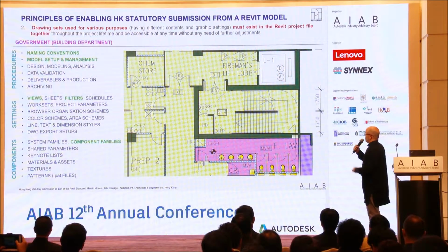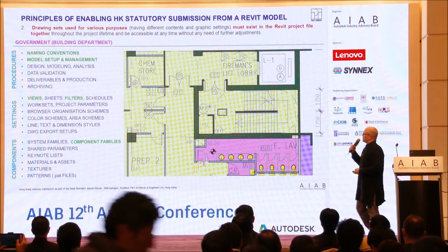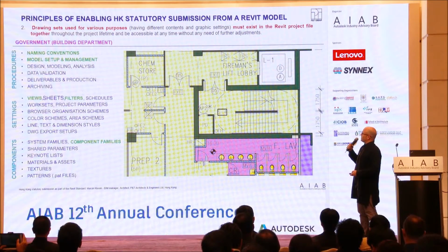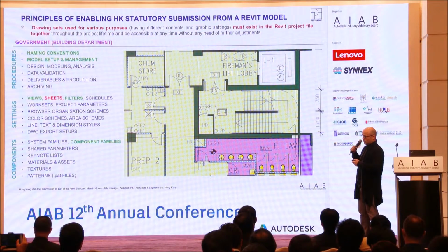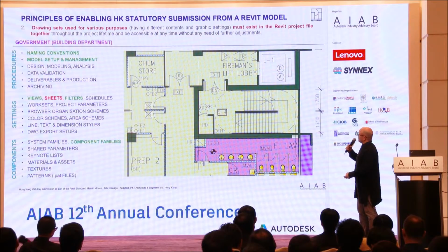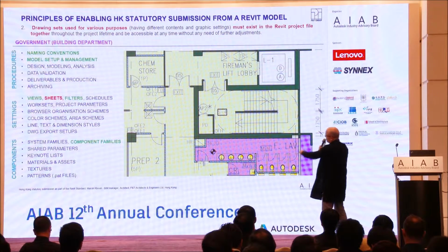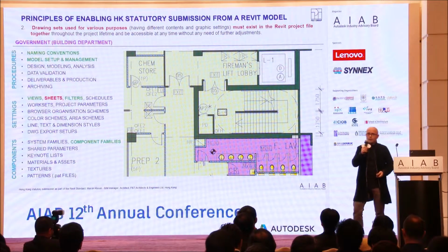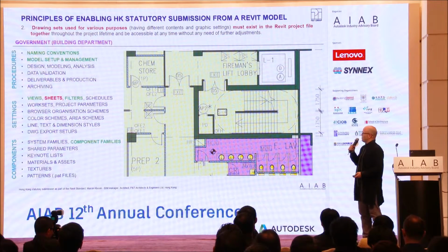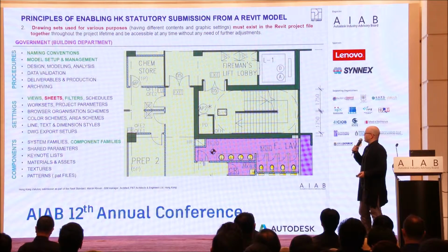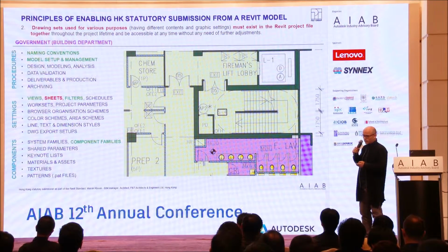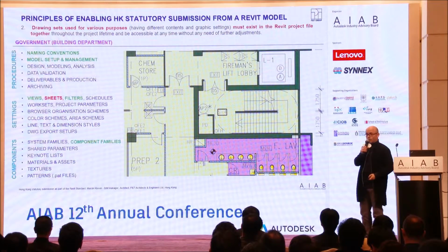Now for the standard GBP submission with colors, we need more than that: sheets. Why sheets? Because in Revit, to achieve what you see on these blue walls pattern over color, you need quite a lot of gymnastics, and that is overlapping plans, two views or more sometimes on one sheet. That's why we need a predefined configuration of sheets and views on them already in our standard.